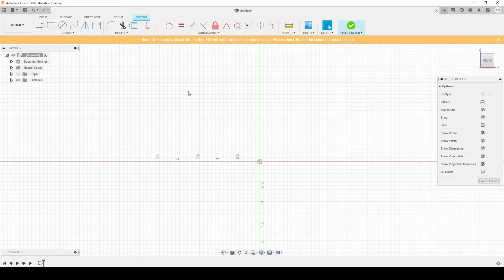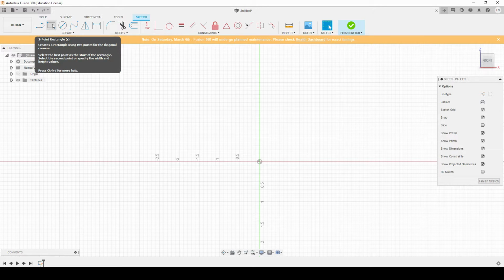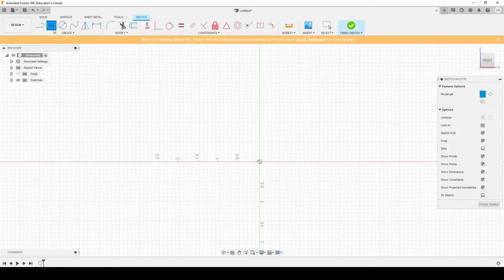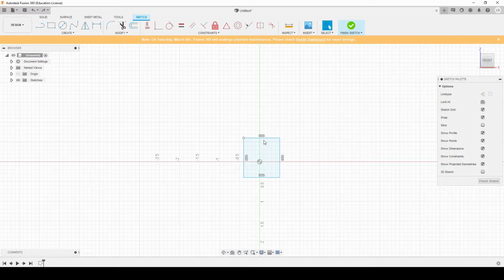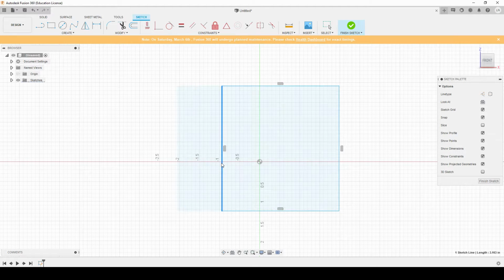So today, how we're going to start this off, we're going to make a pencil holder. To do that, what you may think, we're just going to make a rectangle, a rectangular prism as shown before in the Paint drawing. To do that, you come up here, you click the rectangle tool, and just make a rectangle. Don't worry about size, don't worry about dimensions, just make a rectangle. Now, in sketches, you might see these blue lines. Blue lines mean these lines are unconstrained, meaning that if I click any of these lines, I can drag and change the dimensions however I like. They're not locked in place, they can be however I want them.